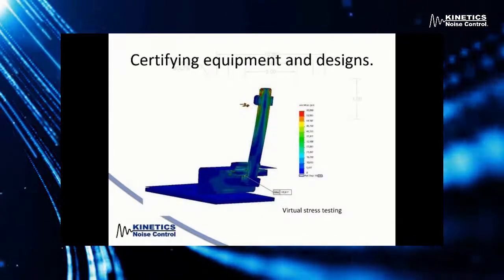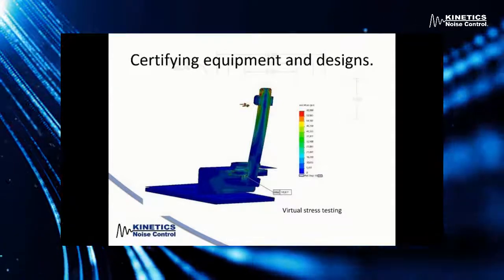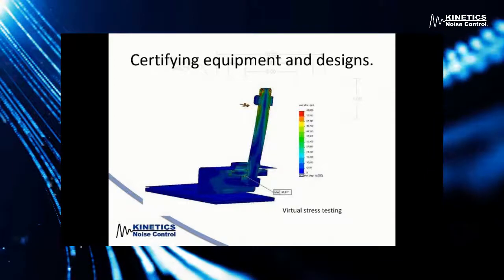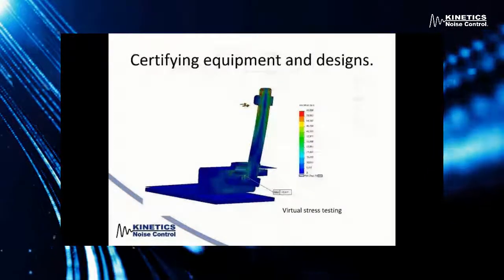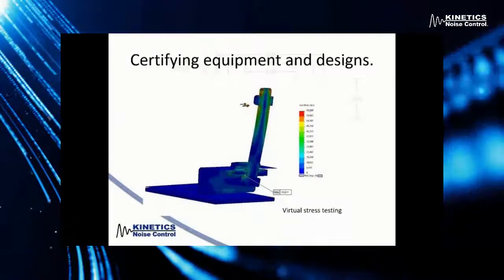It looks like there was a question that popped up in chat here. Let me see if I can pull that up. Looks like it went away. Oh, do you still need an inertia base with springs for a base frame pump with a VFD? It just depends on the frequency of the actual equipment.